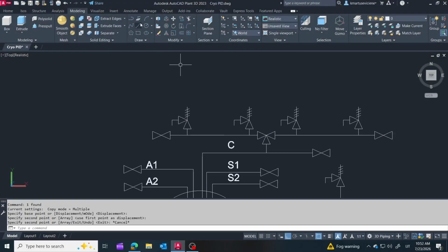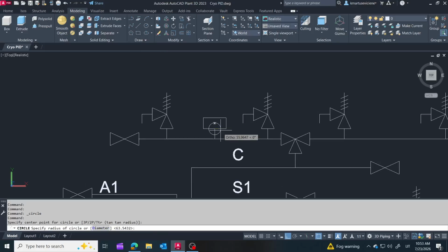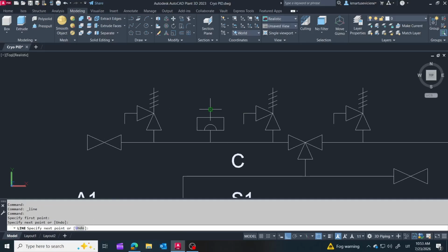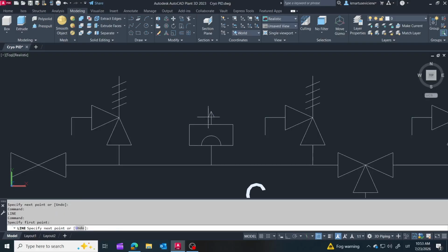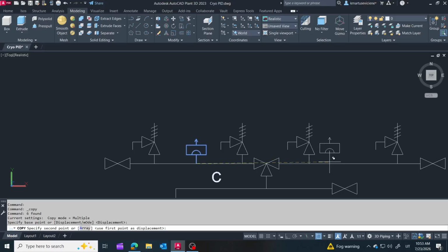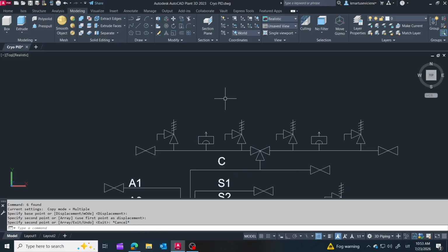In addition to the pressure relief valves, this system also includes a burst disc connected in parallel. Unlike a pressure relief valve, a burst disc is a one-time emergency device. Under normal operating conditions, it never opens. It is designed as the final layer of protection. If the pressure relief valves fail to protect the tank or the pressure continues to rise, the burst disc ruptures, preventing a catastrophic overpressure event.